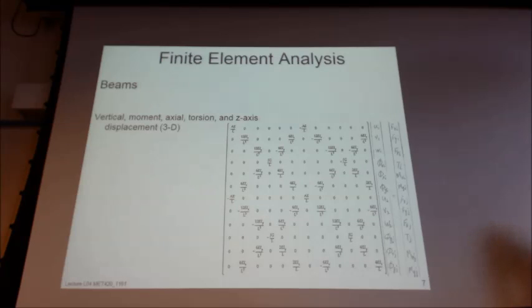We've included all the axes of freedom for 3D for one beam element in each end of it, right? And then you just do the matrix multiplication to determine what's going on for now. Let's see. The one thing that our stiffness matrix doesn't account for is any kind of stress concentrations, right?